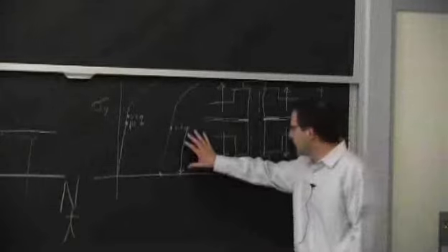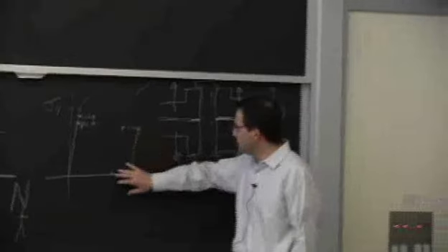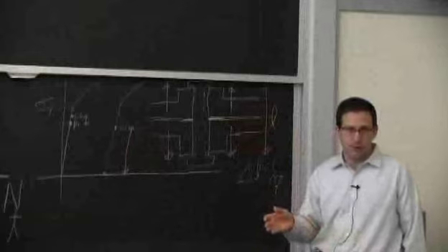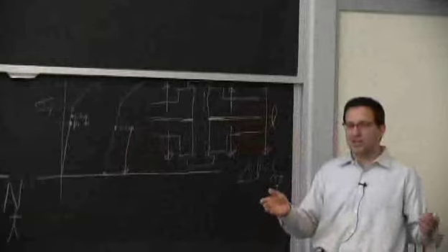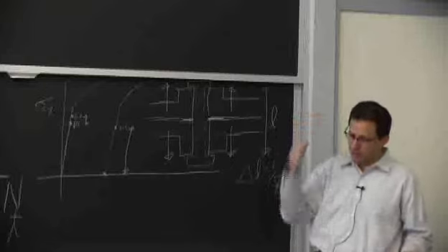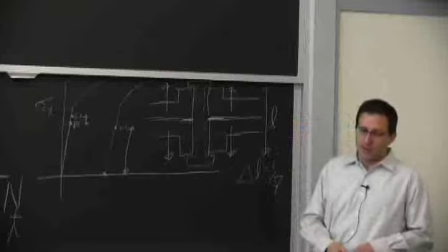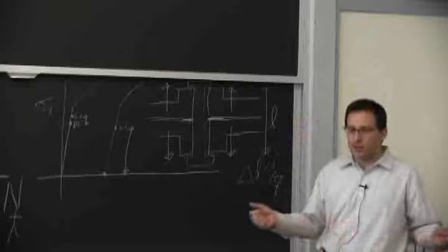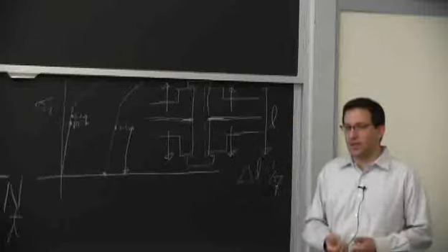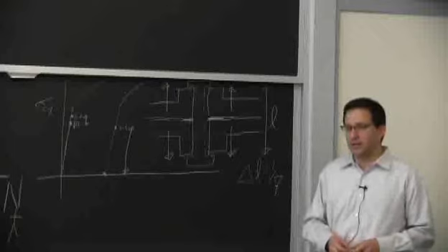And referring back here to the amplitude, the change in amplitude for loaded, unloaded. So it's okay to stress the steel. That's what we do in forming application. You just compress it all the way, but moving it back and forth is another issue. That's where you start initiating cracks. That's kind of the idea here.